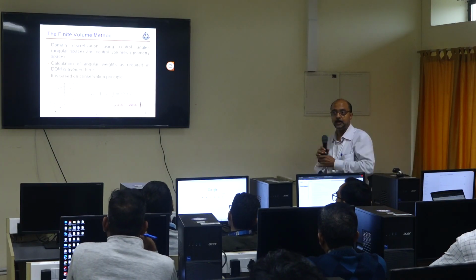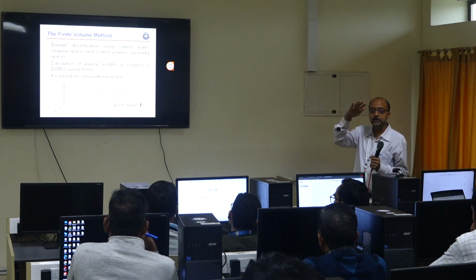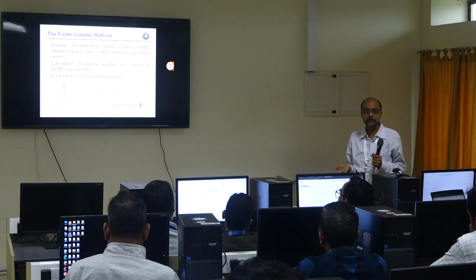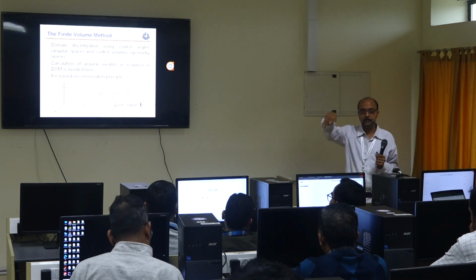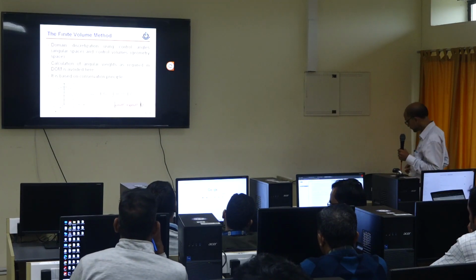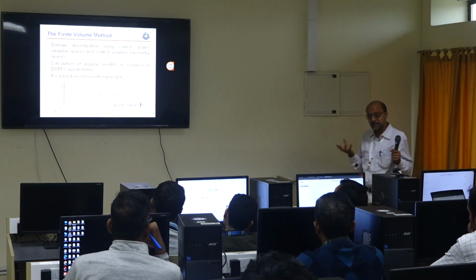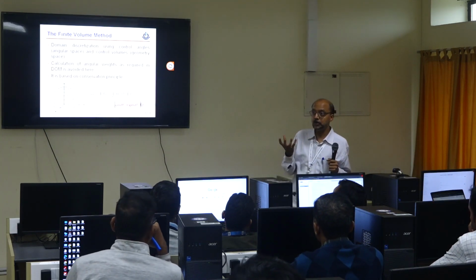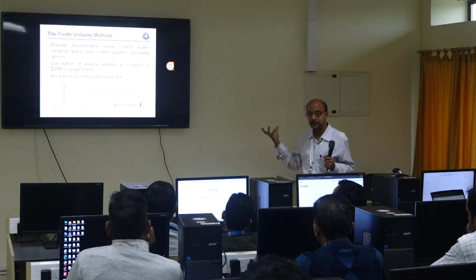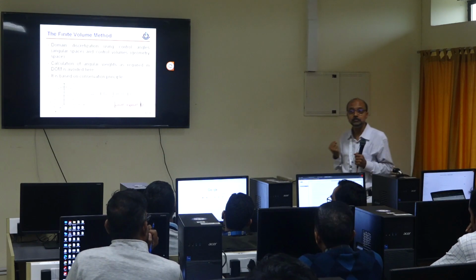Azimuthal means this one and polar means this one. That constitutes the full sphere. The polar angle span is 0 to pi and the azimuthal span is 0 to 2 pi, a full circle. Then you can constitute the sphere. So you can create your control angles as per your requirement, based on your geometrical set. That is quite flexible in developing the control angles using finite volume.